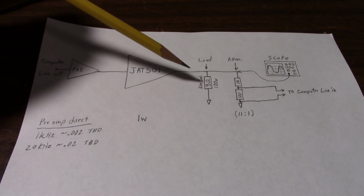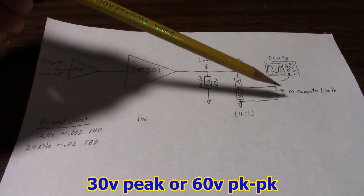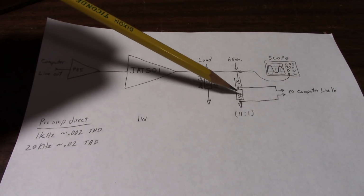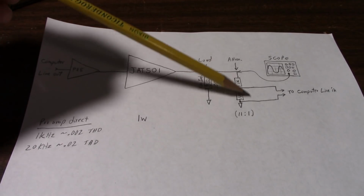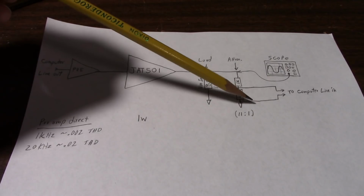It might be like 30 something volts peak to peak, and you don't want to be putting that into the computer's line in port. So you want to attenuate that signal down to something that it could handle. Even though it might have its own built-in protection, at that level you'll just be clipping the signal.